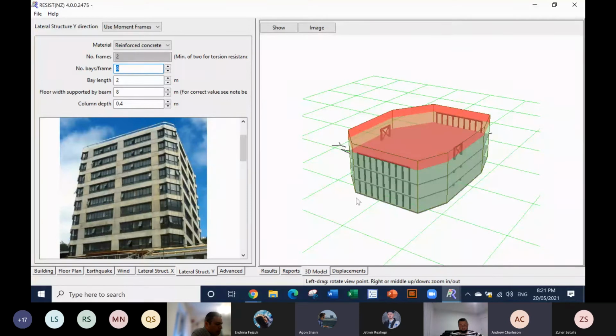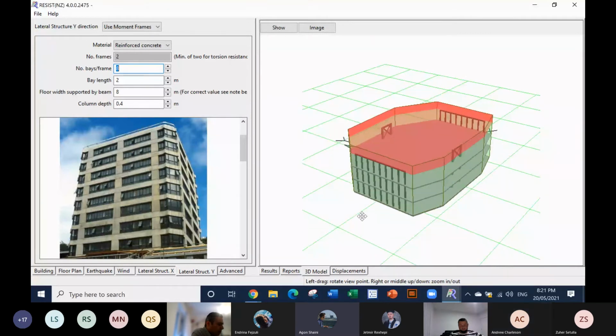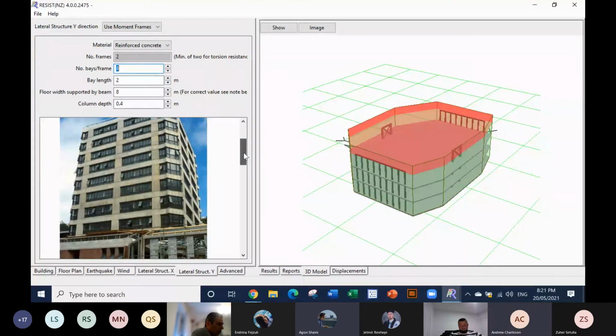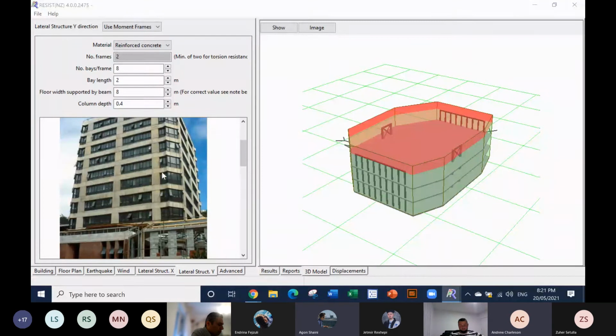Professor, on the other hand, I wanted to add something. Moment resisting frames are mostly used on reinforced concrete structures, but the analysis of the connection is more complex. It's expensive to construct, and the method of stabilization is not as good as braced frames, because we know that the purpose of earthquake engineering is not to build strong buildings that do not experience the slightest damage in rare and severe earthquakes. So the cost of such structures for the vast majority of users will have no economic justification. Instead, I believe that engineers focus on buildings that resist earthquake effects and do not collapse.